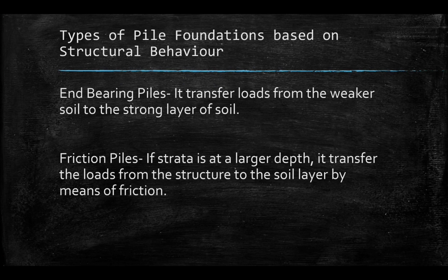So, kapag yung ating hard strata or hard soil is at a much greater depth, gagamit na tayo ng friction piles. So, paano naman yung friction piles? Since hindi siya naaabot sa strata, ang gagamitin lang natin is the friction of the soil around these piles. Okay? So, siya na yung kukontra sa load na bigay ng ating structure.